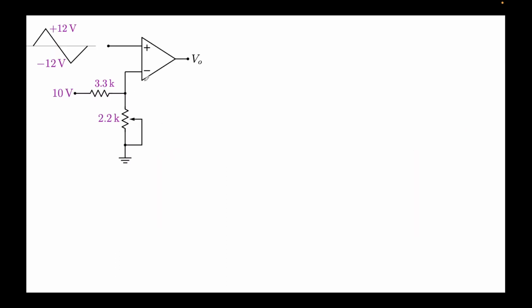So let's do, now we are talking in the top position. So what does it mean in the top position? So this resistor, this will come here, right? So effectively this potential is the same as this potential. This means this 2.2k is equal to 0k. It's shorted. Wiper is in the top position. This means this potential is the same as this potential. There's no resistance. All right.